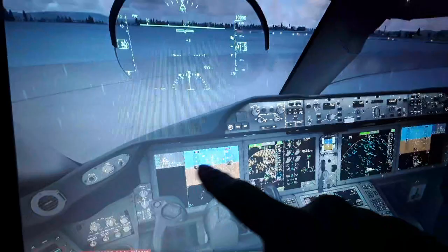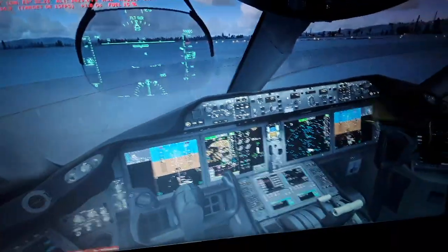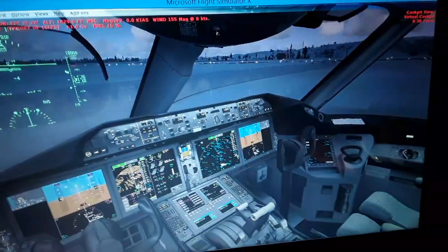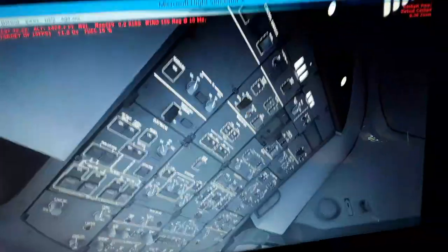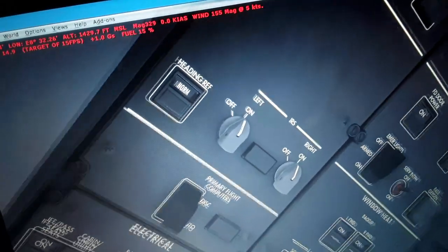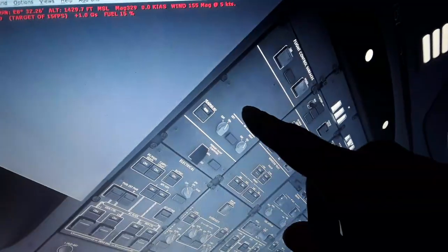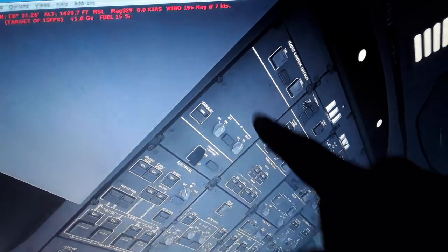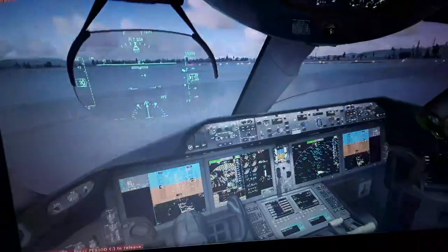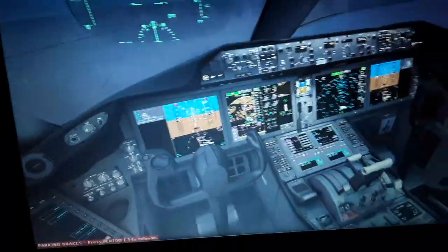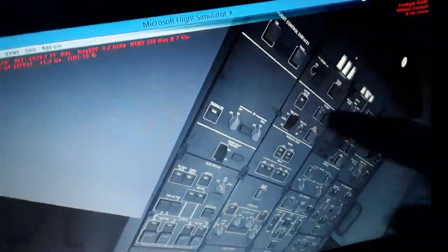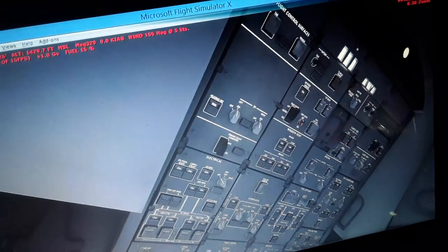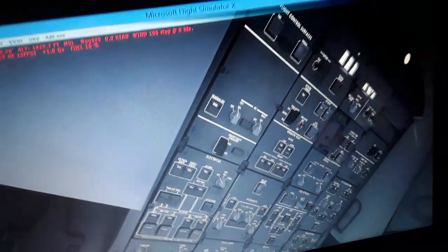So the airspeed you see here and the altitude are functions of the pitot static and pitot dynamic pitot tubes. We have the air data computer over here. You can see heading reference, IRS, inertial reference system for alignment. So this is GPS receivers, pitot static, pitot dynamic, airspeed, altitude difference, laser gyroscopes, and alignment of the aircraft, and also attitude over here, display, progression, deceleration, magnetic north pole, geographic north pole. All these are in the air data computer over here, this section.